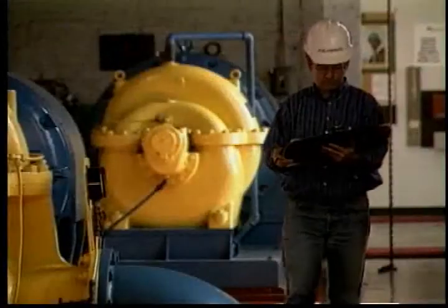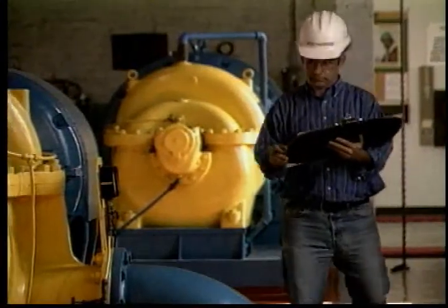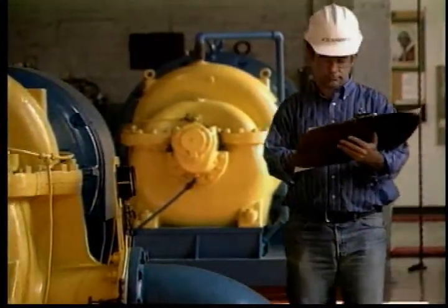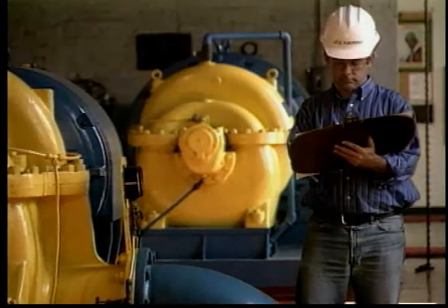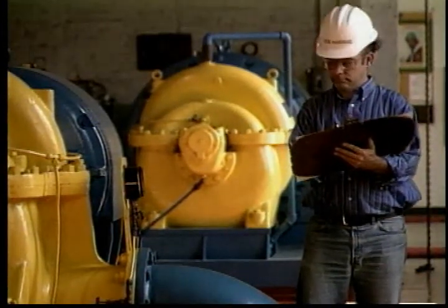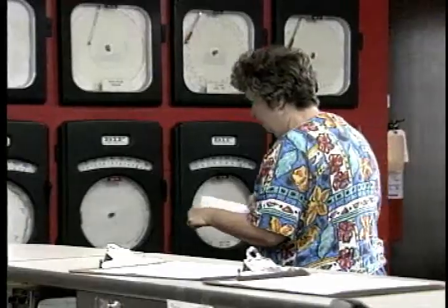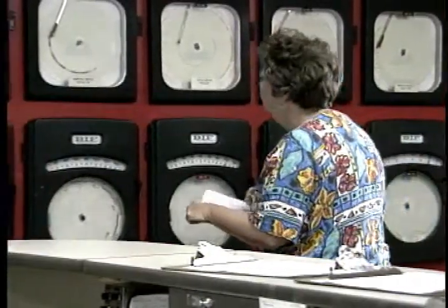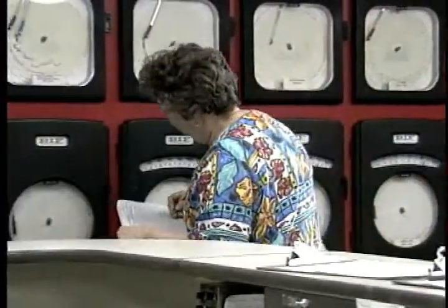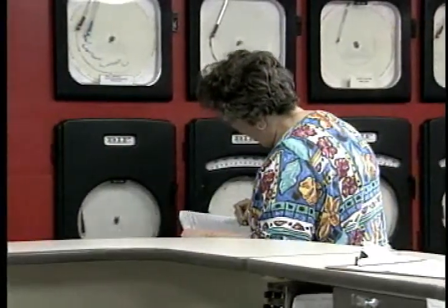The performance curve for any pump describes the work the pump can do and how much power it will require to do that work. The relationship between head and flow and power is the reason why routine, careful monitoring of all 3 factors is important. Any change in one can affect the other 2 and may indicate operating problems.